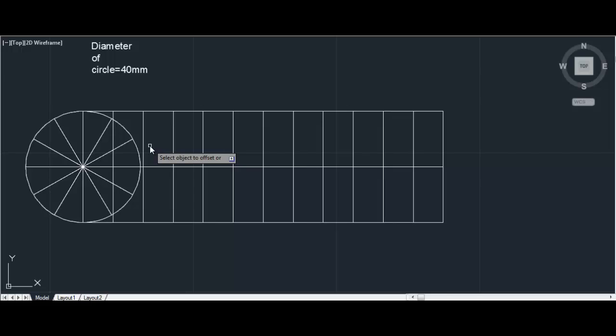Now guys, imagine that the bangle-like structure, like bangles are circles, if it moves on the horizontal ground, the center will be moving in the center line. That is, the locus of the center is this line that is highlighted on the screen. This is the line that the center of the circle will move on. And so we have to draw the circle at an equidistant point, that is the distance is 10.47, so we have to draw a circle with center this point, this point, this point, this and this and this.